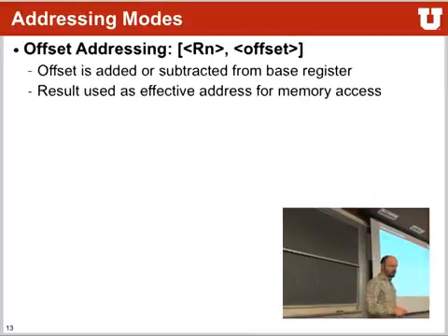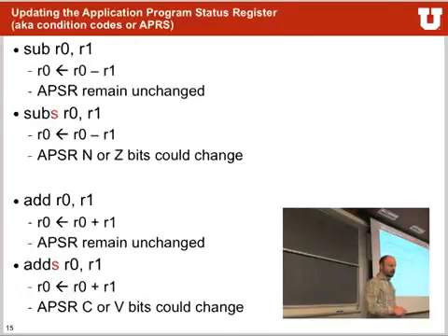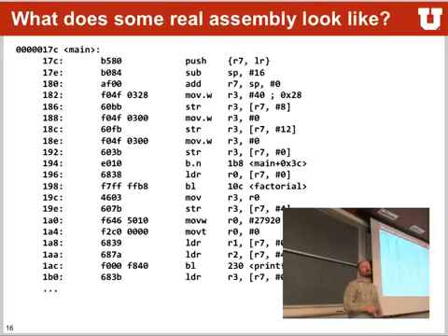We talked about this. All right. So what's happening here? Well, the first instruction is a push R7, LR. Anybody know what a push would do, or an idea of what a push would do? Store something, right? You probably have heard of push and pop, right? C programming, that's when you put stuff onto the stack and away from the stack. That's exactly what this instruction is doing. It's pushing R7 and the link register onto the stack.